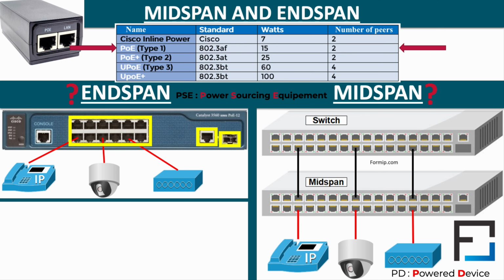Type 1 is the first PoE 802.3af standard from 2003 that delivers up to 15.4 W of direct current to each device. It can be used with UTP Category 3 or 5 cables. This type is very useful for VoIP phones, dual radio wireless access points, and IP cameras, which do not have a motorized function. The second PoE standard, 802.3at, dates back to 2009 and is called PoE+.